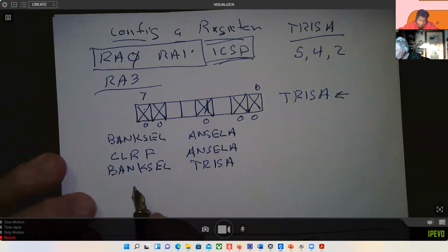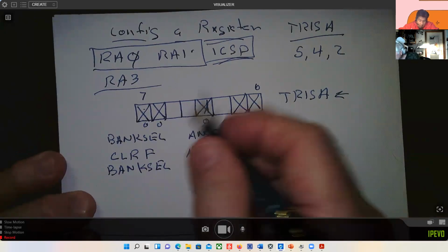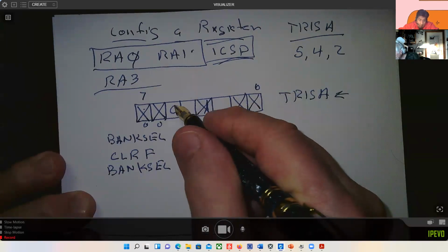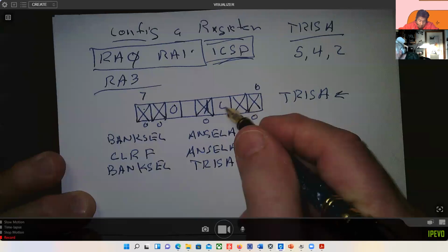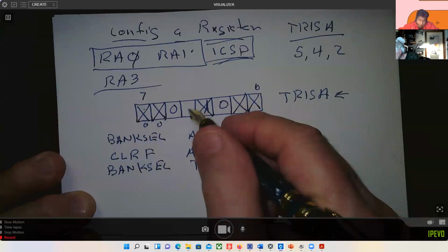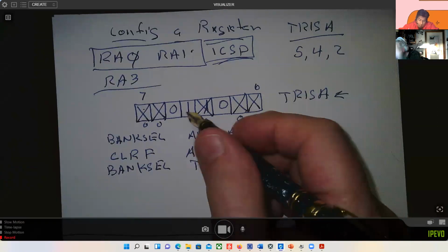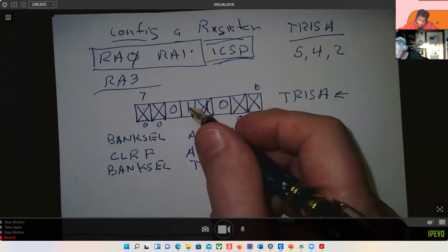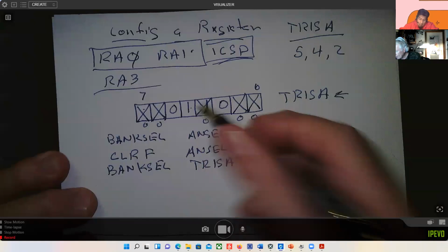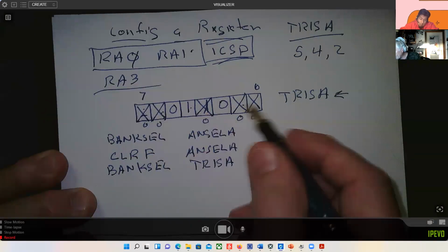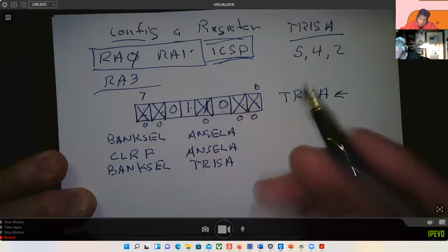Then what I want to do is put a 0 in location 5, and a 0 in location 3. And just for grins, I'll leave location 1, RA4, as an input in case we want to use it for an input. All right, and then these aren't implemented, and these are tied up with our header. So we're just going to write those.